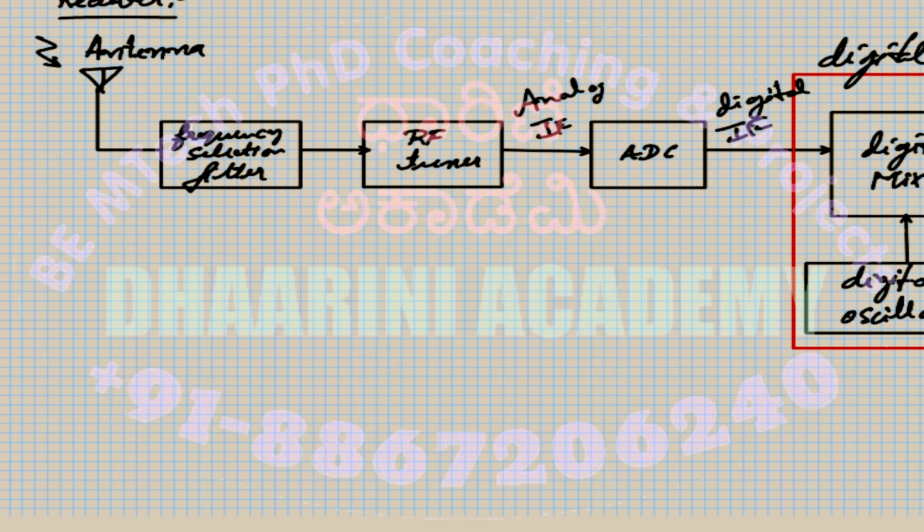You also have the advantage, as I already mentioned, that modulators can be changed as and when you want. So I can write four different blocks of code, one for PSK, one for ASK, one for FSK, one for QAM, etc. Randomly you can switch. Simply switch the code blocks so that you change the whole modulation technique.